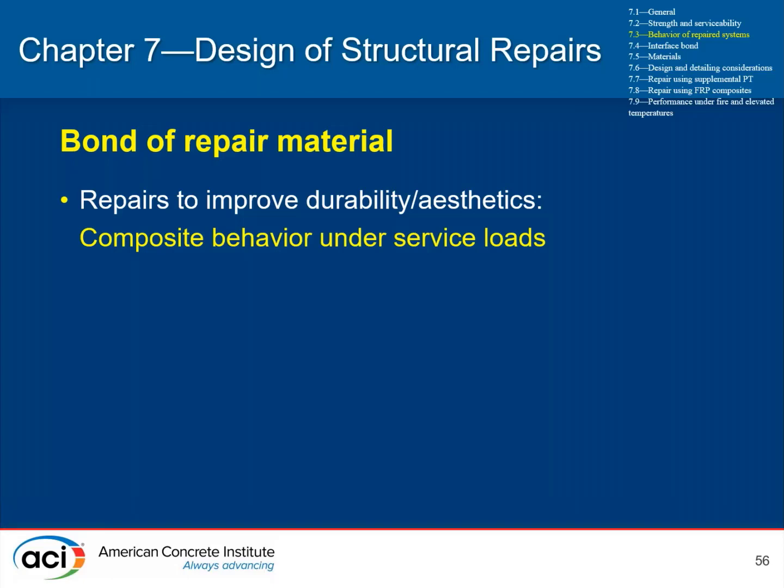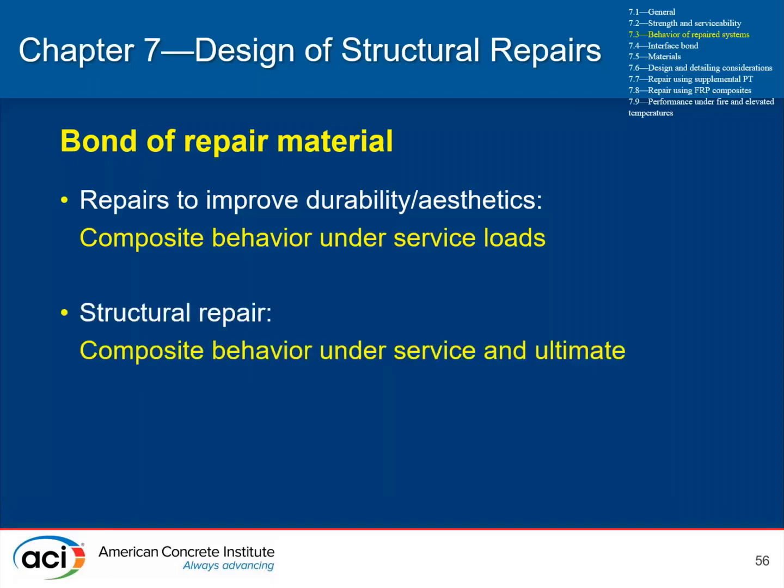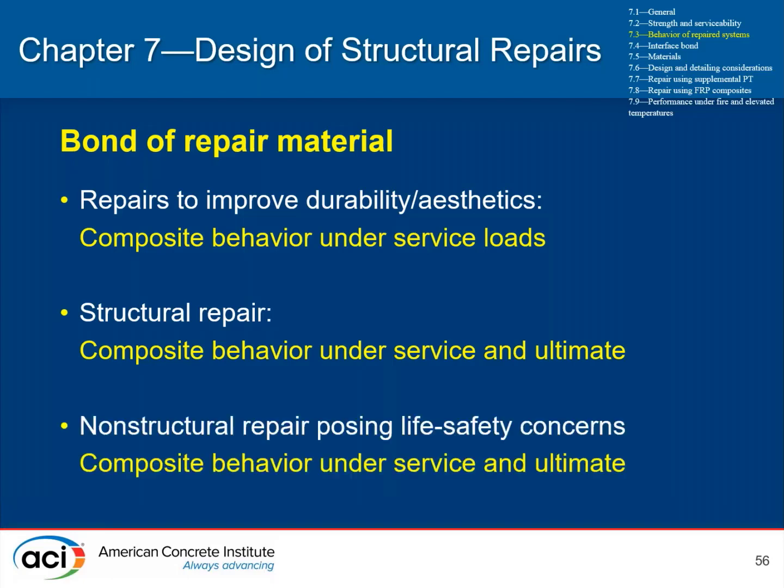When we're repairing to improve just durability or aesthetics, we're essentially looking to make sure that there's composite behavior under service loads. But when we're looking for structural repair, we need to make sure that bond is effective under both service and ultimate states, because it's that ultimate state, obviously, that dictates the capacity of the structure and provides for the safe use of the structure. But also in non-structural repairs posing life safety concerns.